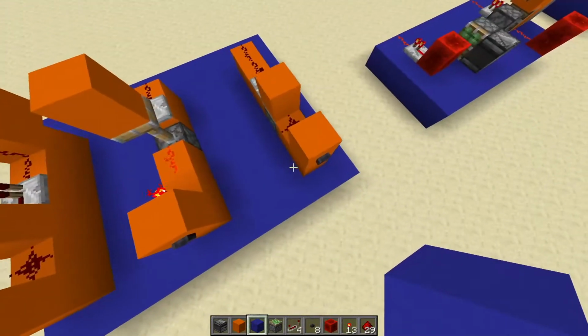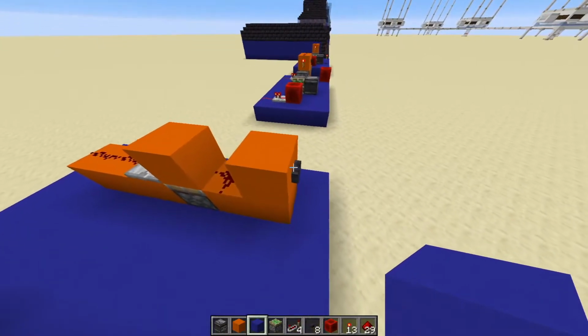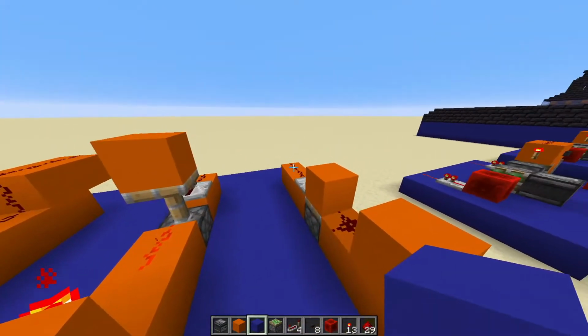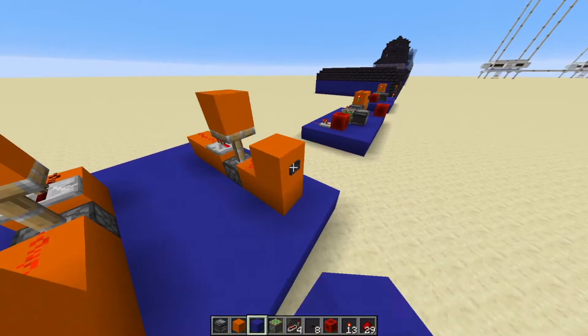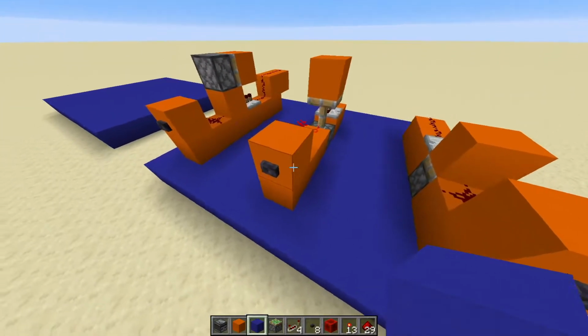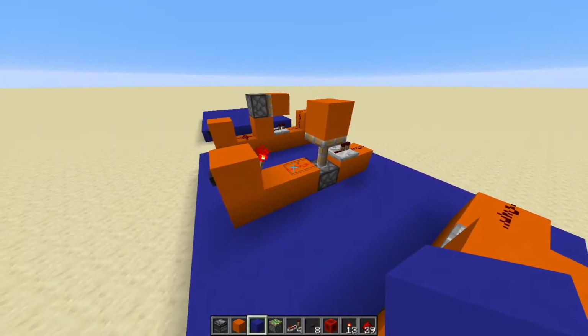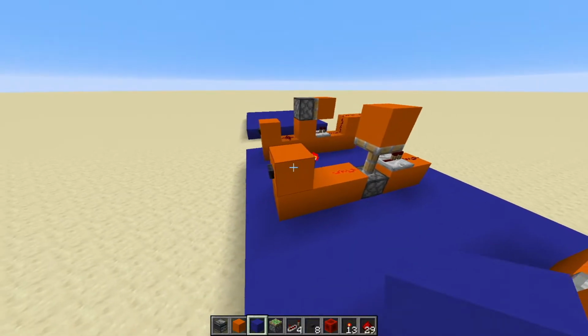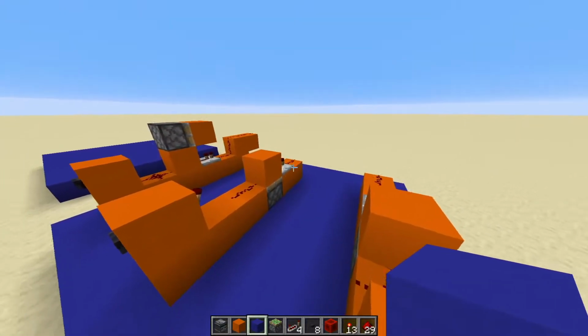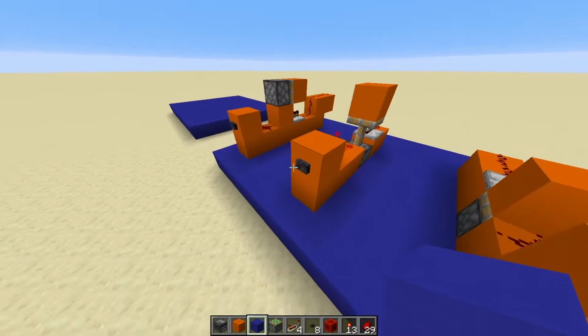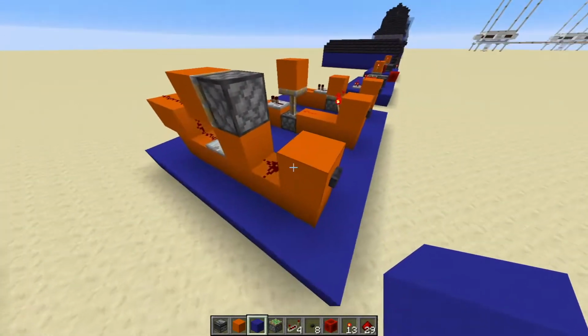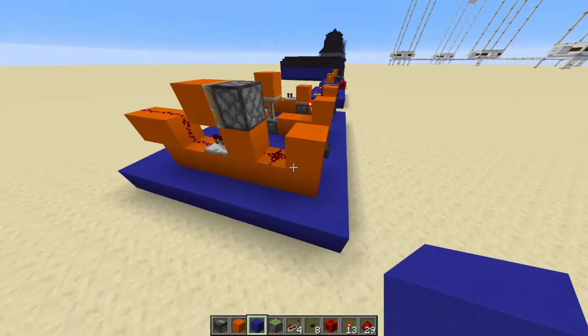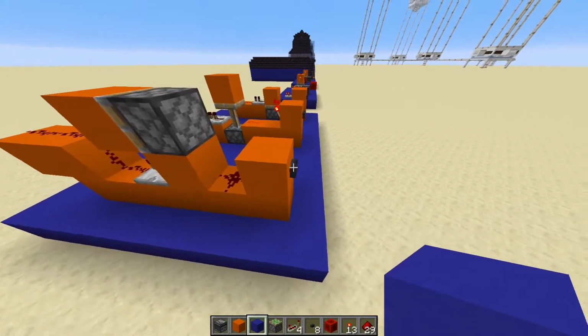So we got three types here. The first is a rising edge monostable circuit, so when we press the button, that will light up over there for one pulse, as you can see, and this is a falling edge one where it lights up on the falling edge of the pulse. So you can see it flash there right as this unclicked. And then you've got ones that do both. So this will flash both on the rising edge and the falling edge.